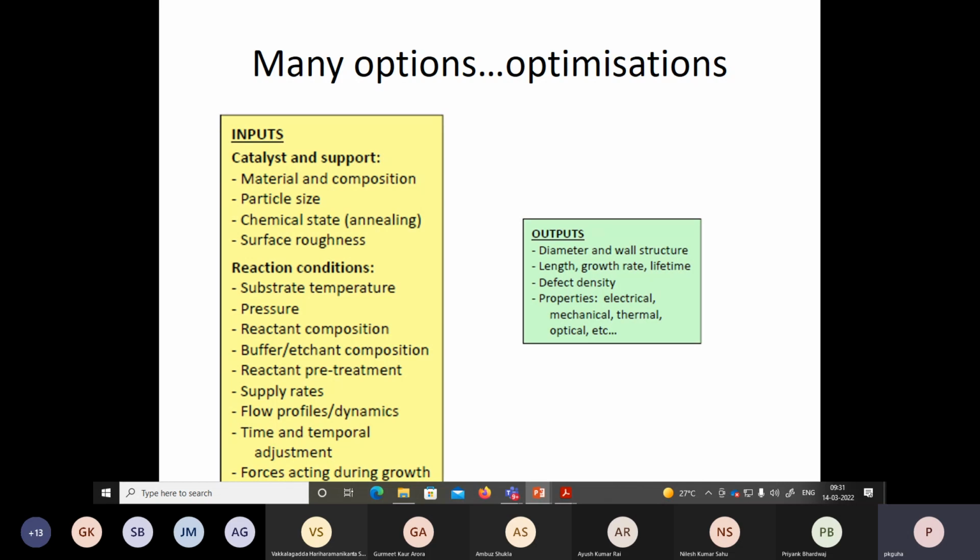Then there are temperature, the chamber pressure, how you are ramping up the temperature, what kind of gases you are using. For example, I talked about ammonia. There are other recipes also. Ammonia helps in dissociating those carbon-like gases, okay, and so on and so forth. So there are opportunities to optimize things. Different labs have their own recipes to develop carbon nanotube depending on their needs.